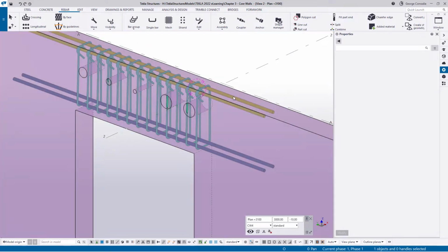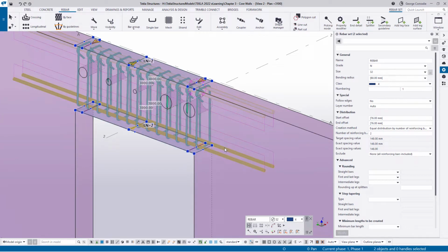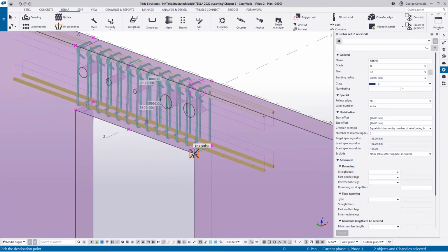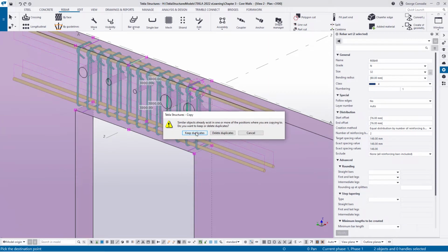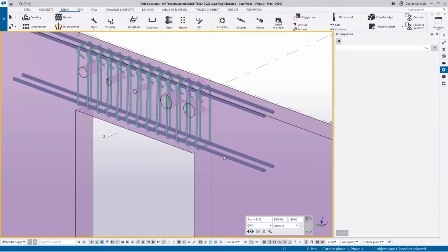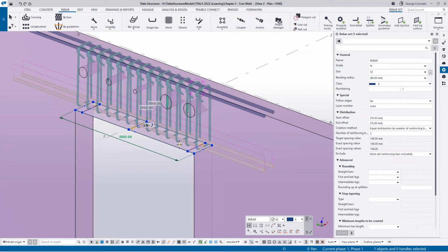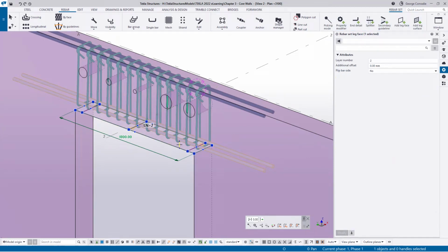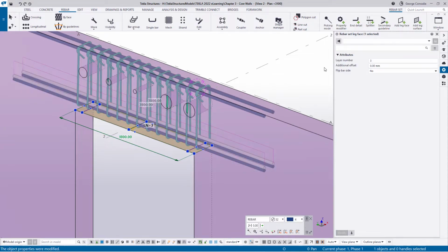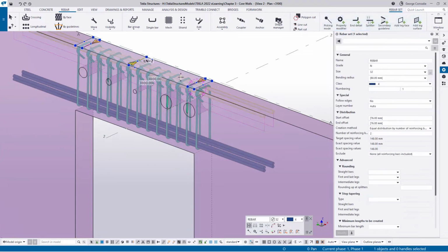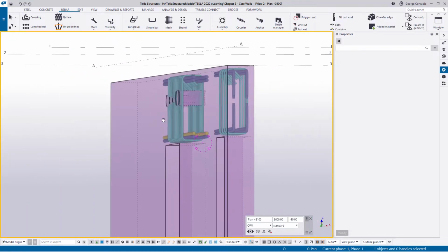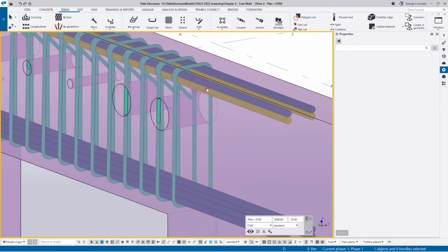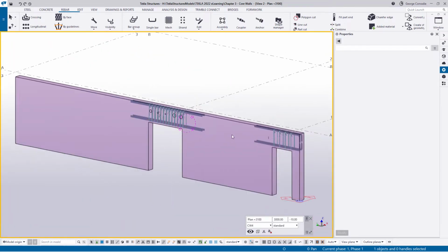So now that we've got that, we can click this set again and that set. We can say Control C, click our origin point, click a destination point in the same part. Tekla says you're about to copy over the other part, yes, and keep the duplicate. And now, just like before, we can click on any set, click on the actual leg face, just make sure it's switched on here under visibility, and then we can change 2 to 3, and it will add it on top of that one. And we can do the same here, click on the face and move 2 to 3. And just like that, we've got two sets of rebar groups on top of each other, nicely inside of our ligatures, extending into the wall, and that takes care of the two headers.